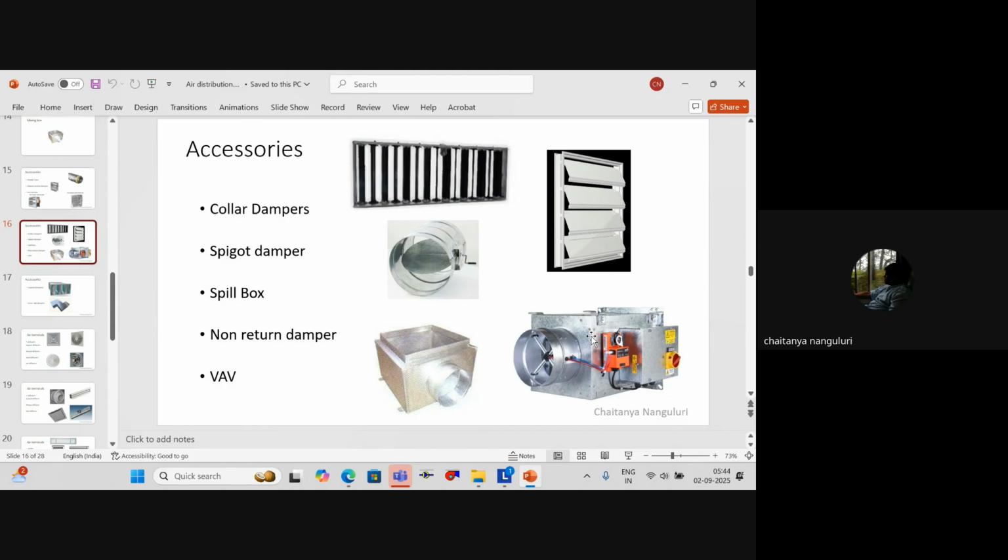For you to understand it briefly, basically it's hardware that is used to control the airflow according to the temperature of that particular room space. That means you can control a particular zone's temperature using this variable air volume damper. Whenever you have a VAV, unless it's a bypass VAV, if it's a normal VAV, it's mandatory for you to have a VFD. Those concepts we'll discuss later. Is it fine?